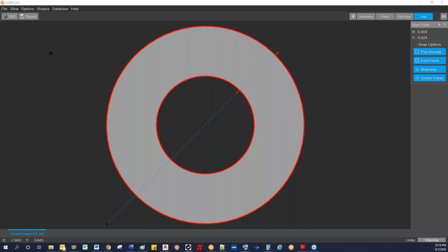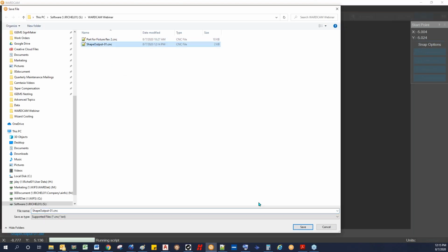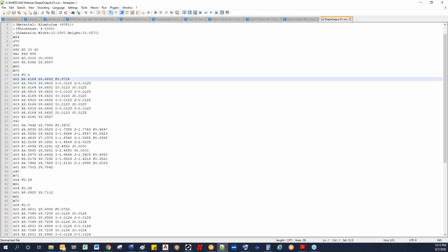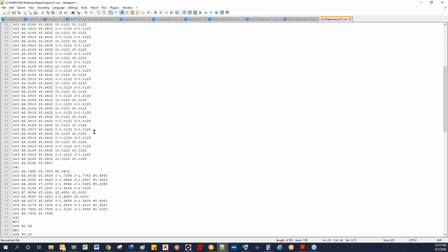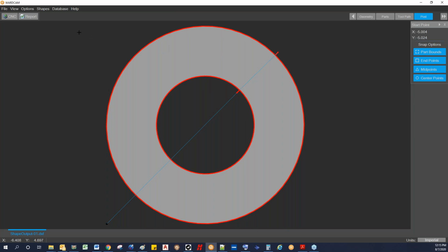Let's try this. All right, sorry we're going through all that with my screen pause. So basically what you'll see here now is that, let me go ahead and make the CNC file. We'll go ahead and overwrite this. So now we've got the extra pierce turns, but it's doing it at the slower feed rate of the initial piercing. Since I was not sharing the right screen before, let me just review where I was going here.